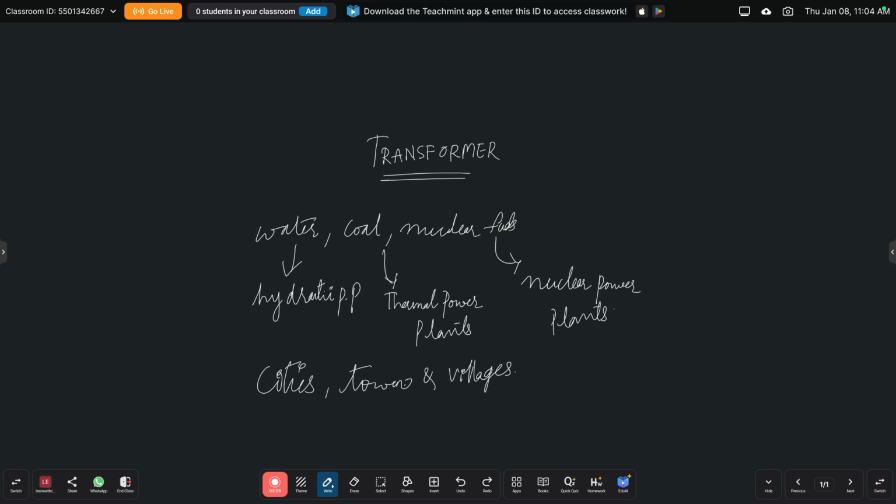The electrical energy is usually generated at 3.3 kV, 6.6 kV, 11 kV, or 33 kV. Transmitting the electrical energy at these voltages is not economical, due to the more voltage drops and ohmic losses in the transmission lines.